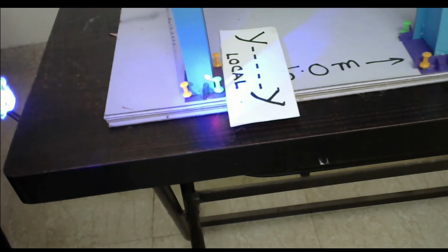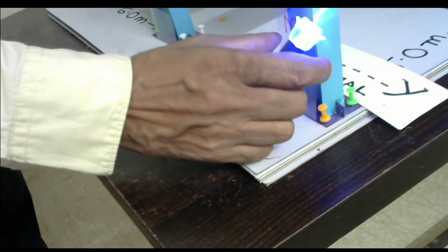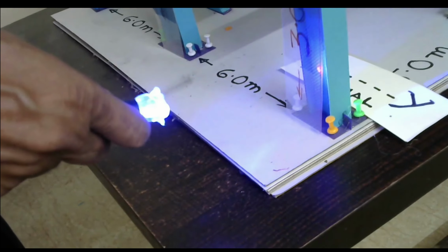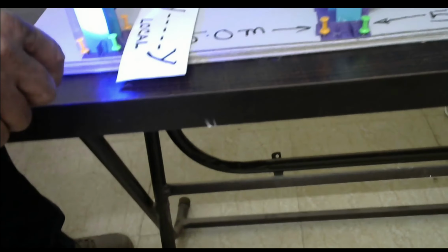So you can see, if we come to this direction, there is a flange here, and there is a flange here. So for this direction, this is a moment connection because the flange is contributing. So enough restraint, we can consider this a fixed connection, but along the YY direction, there are no flanges.